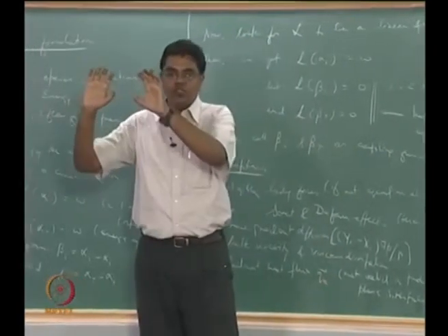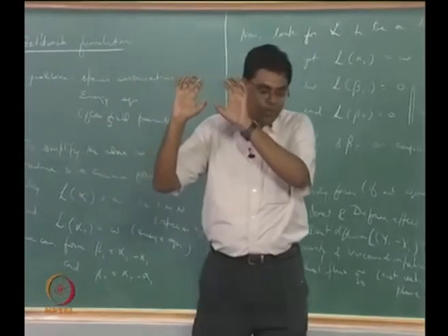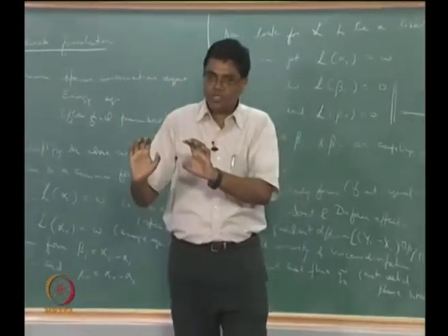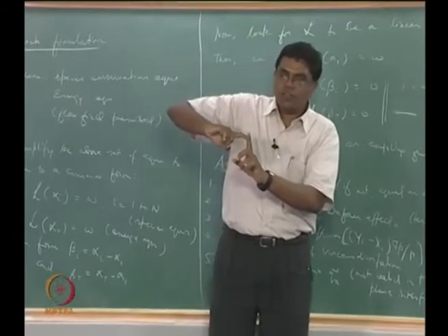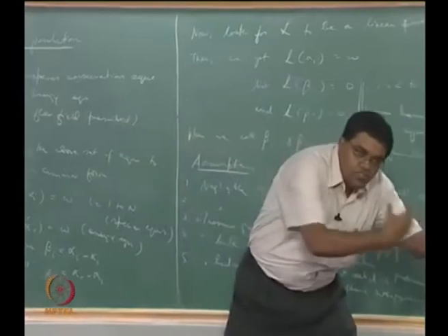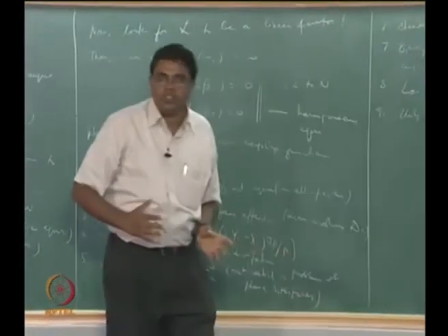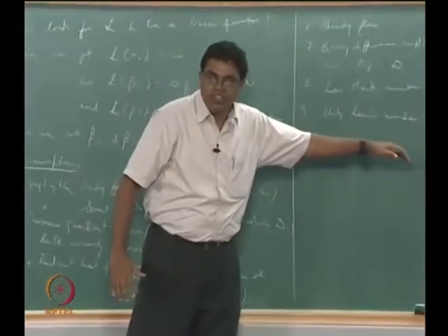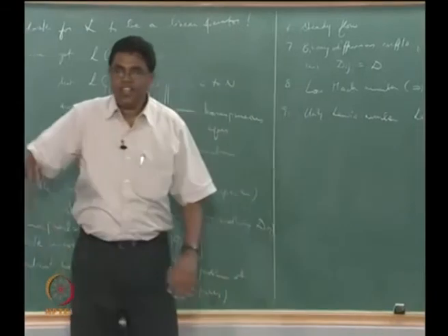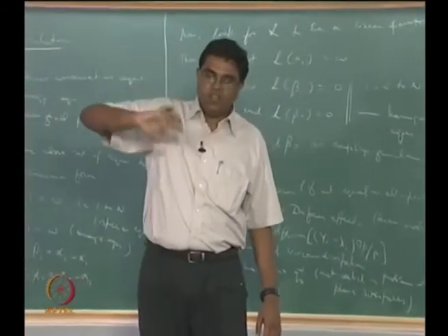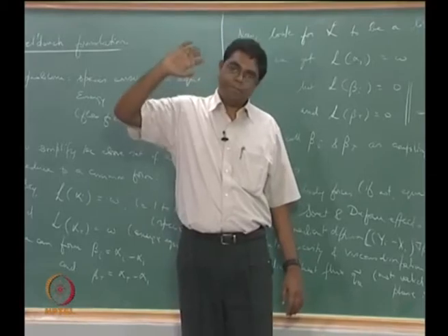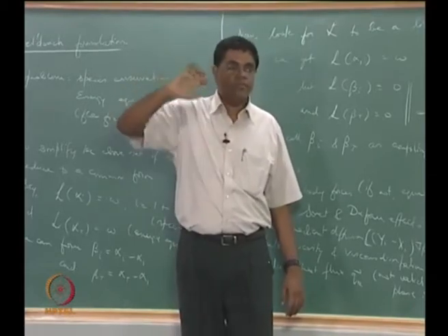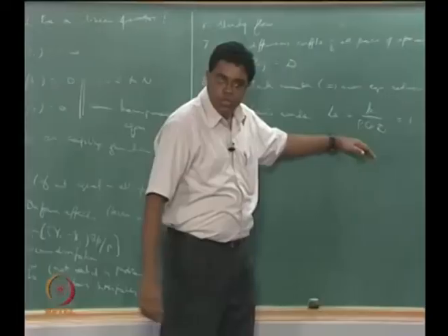If these two terms should look similar for the species conservation equation and the energy conservation equation, then we should be looking for the transport terms to be comparable. So if you have a species which is diffusing so fast but does not conduct heat a lot, that means it has a non-unity Lewis number less than 1, then the transport terms or the diffusion terms in the species conservation equation and the energy conservation equation are not going to match up. You are going to have a problem. So the only way we can get these two to look similar is if you have a unity Lewis number.